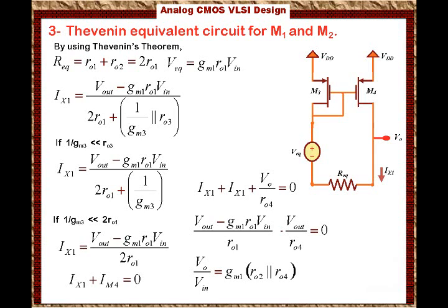You make the gain of the op-amp so large such that if we use it in a feedback circuit, you have accurate gain. The idea here is to use feedback for accurate gain, but to design the transistor level op-amp or amplifier with approximation, but make sure it works.